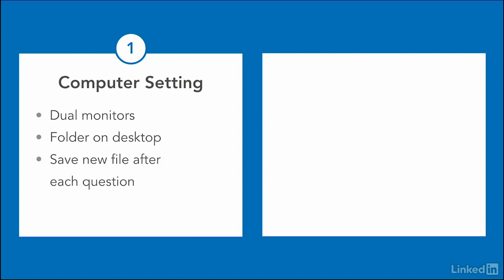The next thing I want to point out is definitely make sure to save the part from each one of those questions after each question. So question number 1, when you finish it up, definitely save a copy and then move on to question 2. When you finish question number 2, save a copy, because a lot of times you're going to find an error in your part and need to go back and look at the previous question and modify the answer.